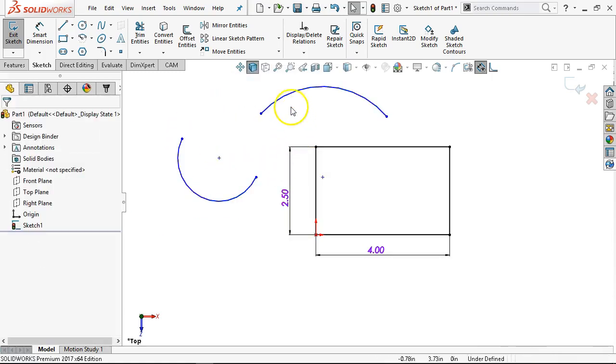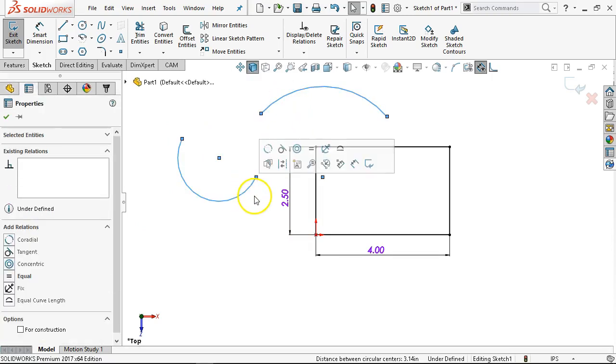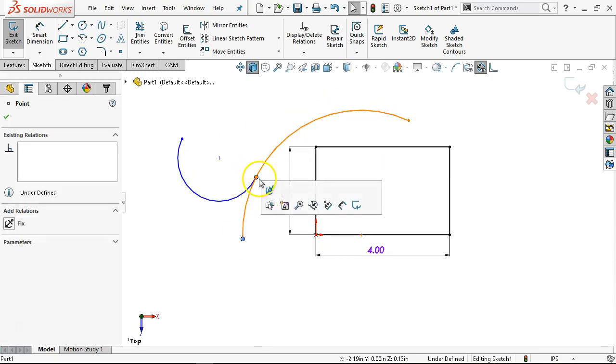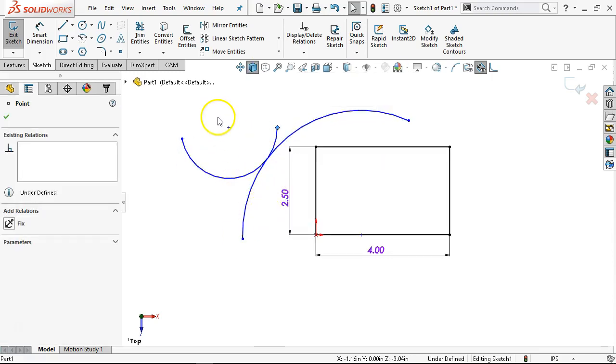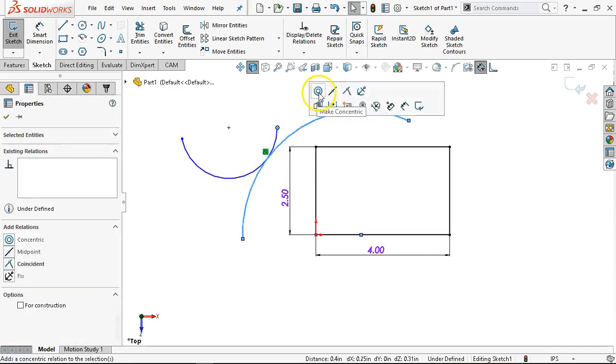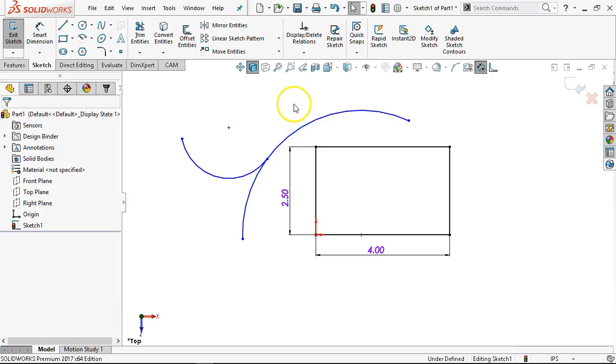We go to the tangency, so arc and arc, and go to tangency. It's just shifting its position a little bit. Same thing. Selected first, selected second. When I drag this out, I'm going to be looking at those tangency locations. And when we get to a point where the endpoint and the other arc go to coincident, then that is my tangency point.